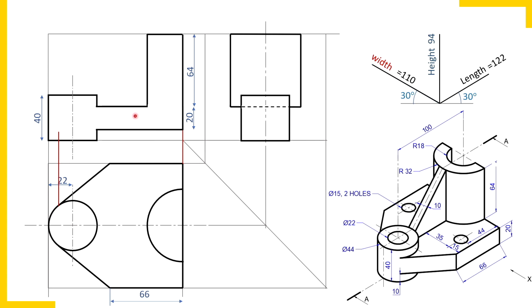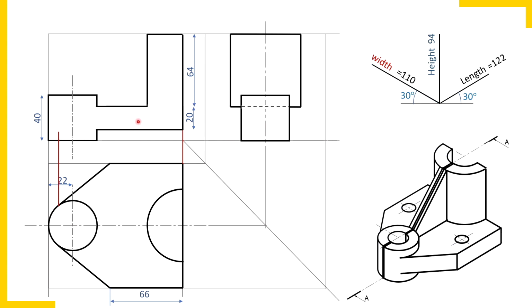Okay, let's proceed. This plate I'll complete in the side view. The plate of 20 mm height we will draw in the side view. So in the side view also, as usual, a rectangle. Which two dimensions do you get in the side view? Height vertically and width horizontally. So height, draw end projectors suggesting the height of this plate.